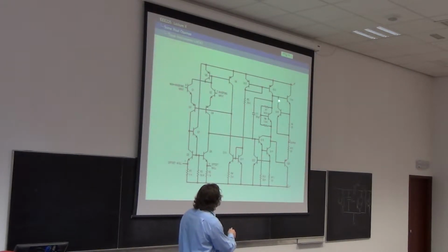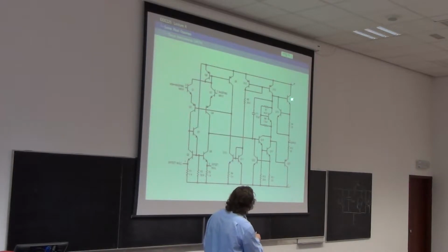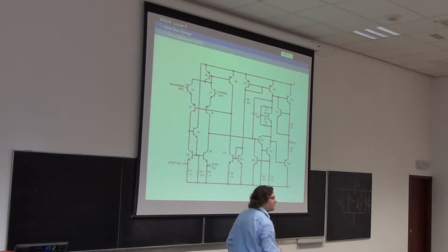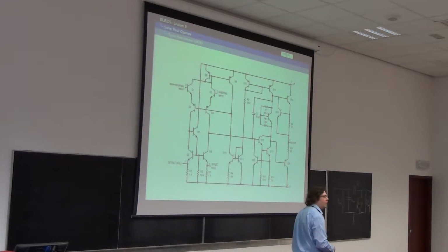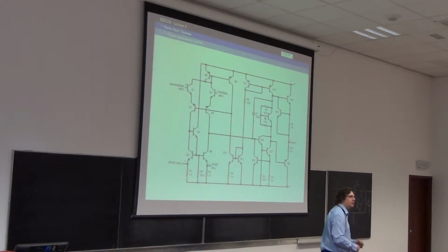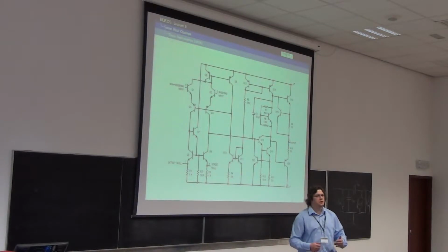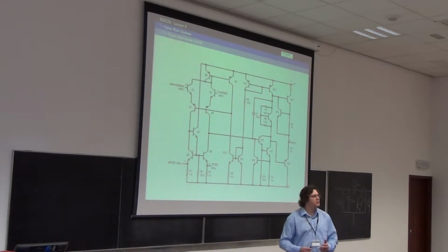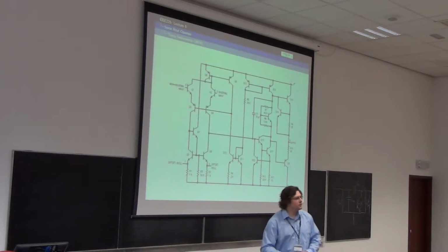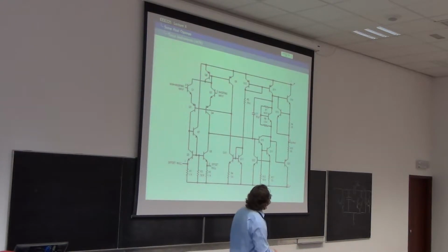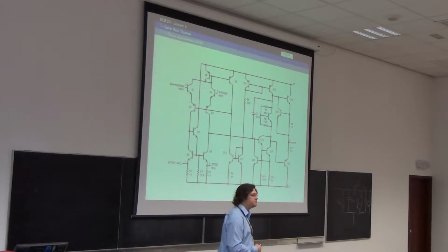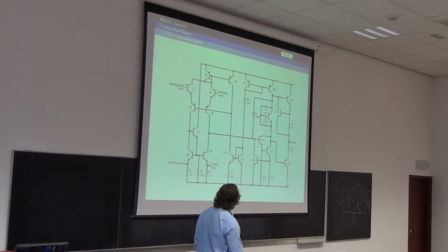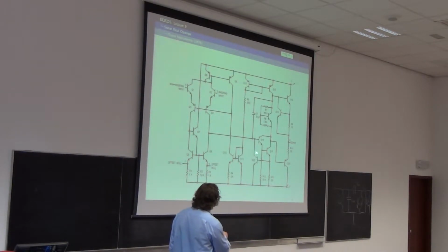And the theft of this base current will turn off this transistor a bit, because you put a VBE on and a certain IB flows, or you force a certain IB in and a VBE, which is just right, appears. You can't have one without the other. So the theft of IB means that Q14 is going to have to turn off a bit, which saves it from destruction. Similar arguments apply to this transistor here, Q22.